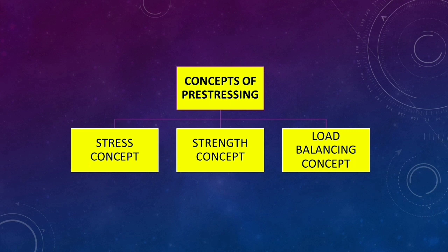Prestressing is the initial application of stresses to a concrete structural member to counteract the undesirable stresses caused due to working loads. Prestressing is commonly introduced by tensioning the steel reinforcement. Three concepts may be applied to explain and analyze the basic behavior of prestressed concrete. These concepts are: first one, stress concept; second one, strength concept; and the last one, load balancing concept.